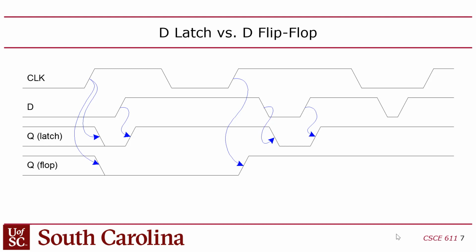In this case, you have a rising edge of the clock here. D is high. Q was low and transitions to high in response to that. You guys see that? So in the case of the latch, now at the beginning here, both of these are don't knows. Notice that there's a line on the top and the bottom because I don't know what the initial condition of Q is. But the first time Q changes, I know what Q is.